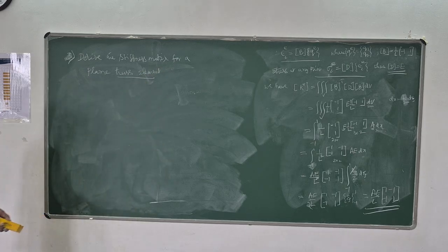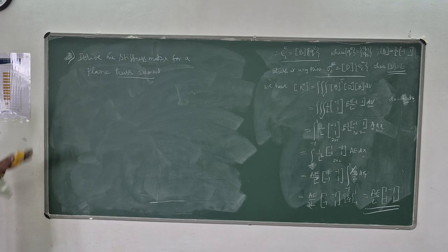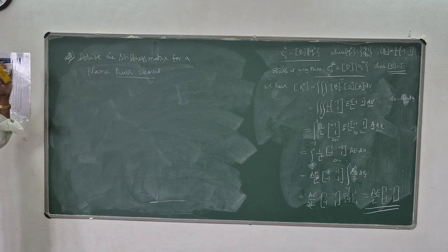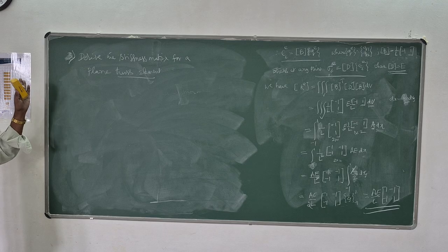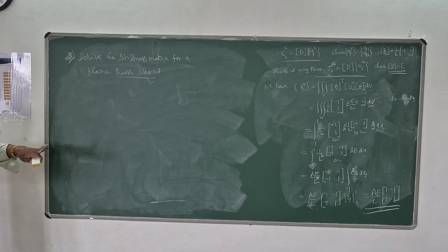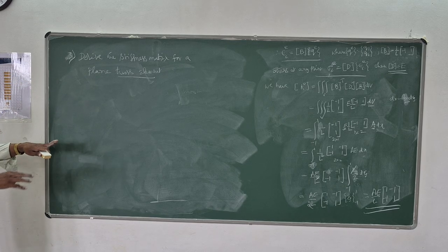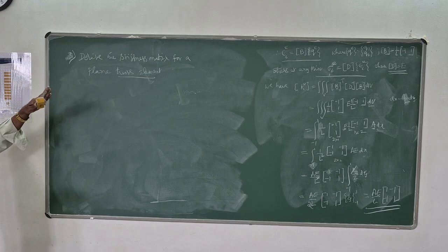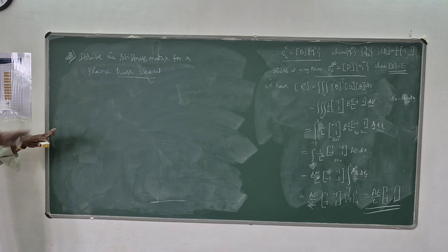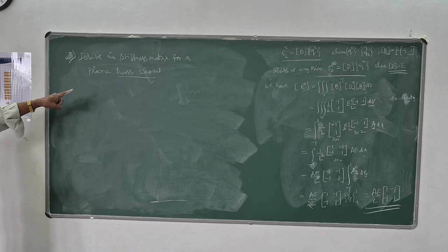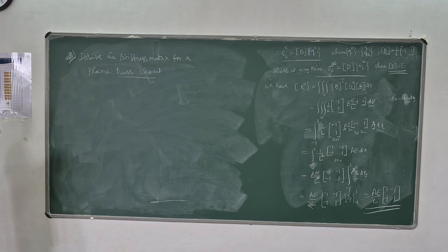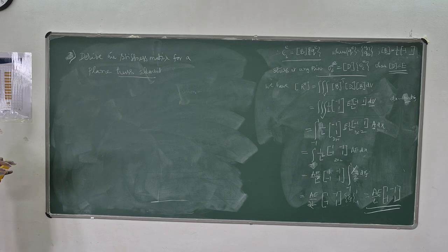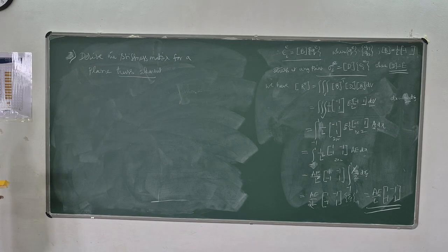The difference between bar and plane truss element is that a plane truss element can assume any shape, any direction, whereas a bar is always either horizontal or vertical. Even if it is inclined, load will be only along the axial direction. But in a truss element, load can be acting at the nodal points, and it can be in any direction.